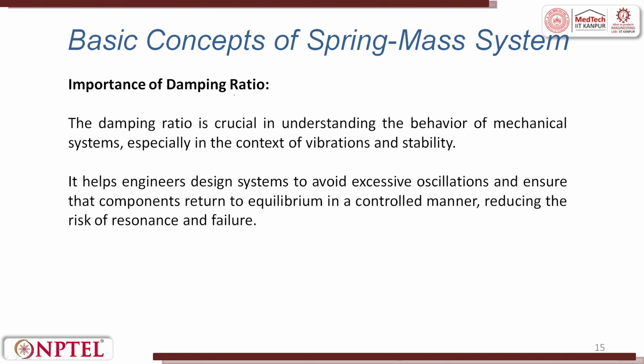So, importance of the damping ratio. The damping ratio is crucial in understanding the behavior of a mechanical system, especially in the context of vibration and stability. If some object keeps on vibrating, then it is going to bring a lot of uncomfortable situation for the object or the system. Stability is very important. It helps engineers design systems to avoid excessive oscillation and ensures that components return to equilibrium in a controlled manner, reducing the risk of resonance and failure.